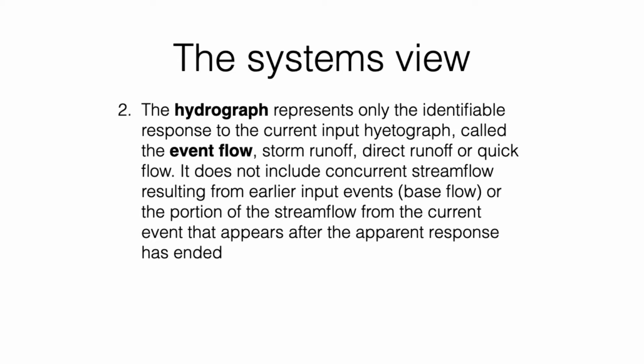The hydrograph produced only accounts for the event flow, so it is the response hydrograph. Base flow must be determined in some other way. However, as you know, base flow does not change much during any given event, and therefore base flow may be assumed to be a constant addition for the whole duration of the response hydrograph.